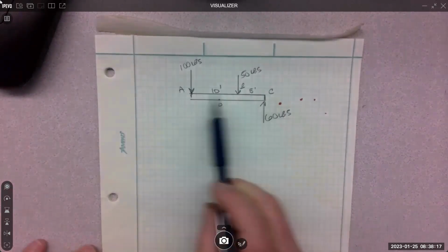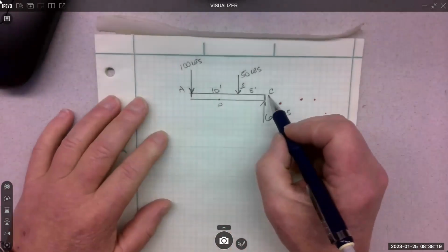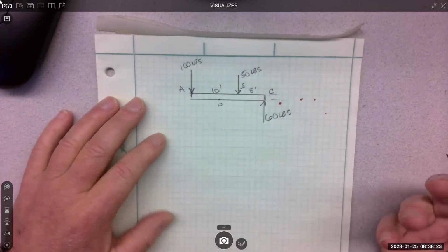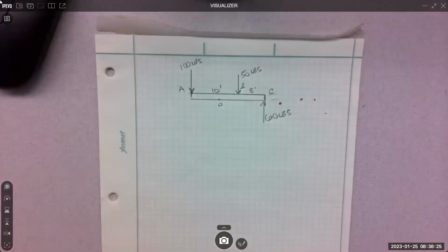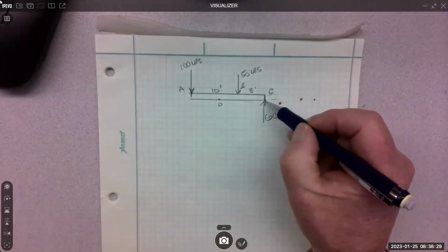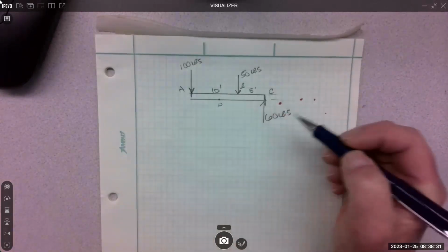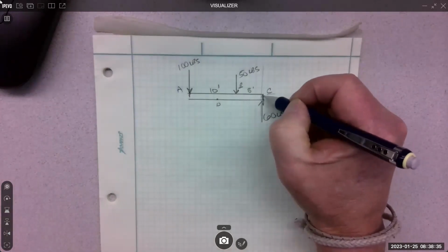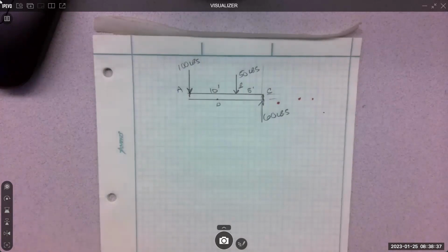If they give you a beam and they don't give you the thickness of the beam, which is very common in the book, then we just neglect the thickness. It's like a thin line thing, okay? So even though I might draw this down here, the point of application is there, here, and here. Remember, we do have transmissibility. This could actually be drawn up there, and then everything's in line. So just don't have heartburn over the thickness of the beam, because they'll not give it to you most of the time. Just ignore that.